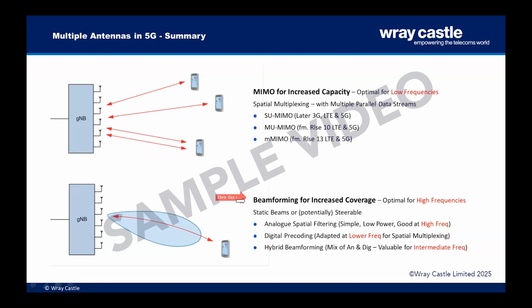The first technique that we will use is beamforming. The action of beamforming is to get the antennas to work cooperatively together so as to focus the intensity of the radio beam towards the desired target upon the downlink, and to focus the reception beam towards the desired transmitter upon the uplink. And by focusing the signal energy in this way, it will improve the coverage of the system and thereby will deal with the problems encountered at high radio frequencies.